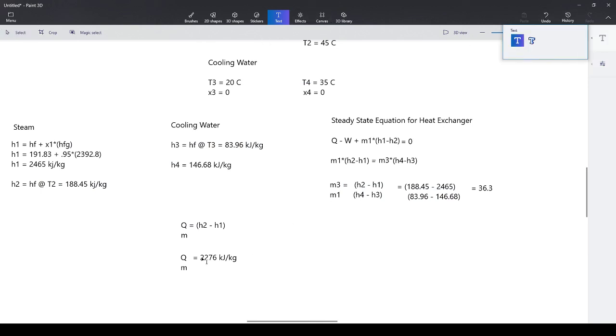The point is that you have to be very careful with how these come out. And now I have a negative number. Look at that. See? And so, be careful with how they come out at the end. You have to know which fluid is taking heat in or which fluid is losing heat. That's what you need to know by looking at the question and reading the values. If one fluid goes up in temperature, it means that that is the one that's gaining the heat. And since it is gaining heat, the other one is losing heat. So the other one's heat transfer is negative. The one that is gaining heat is positive.